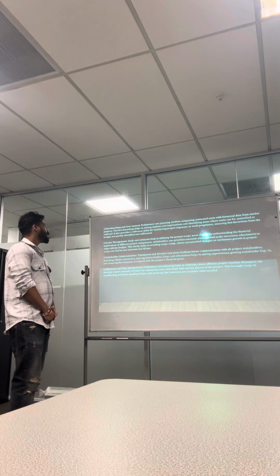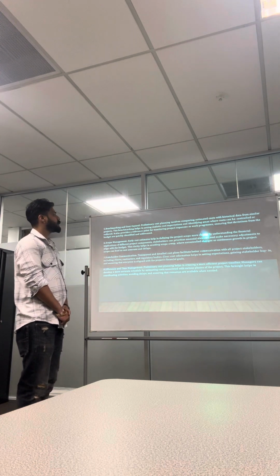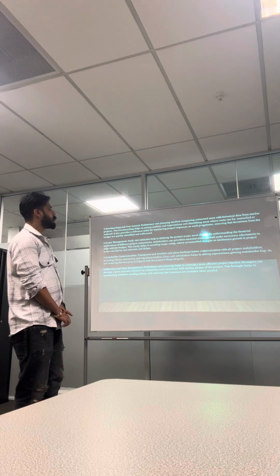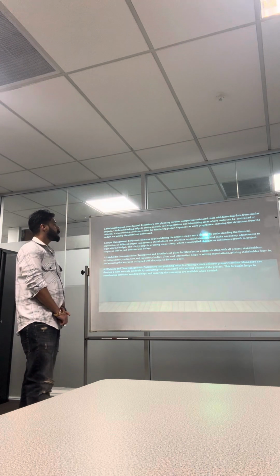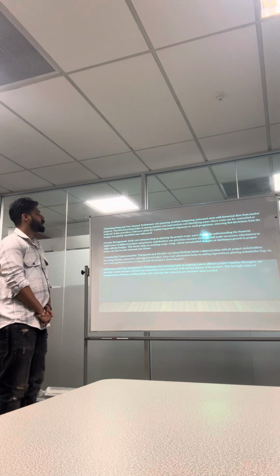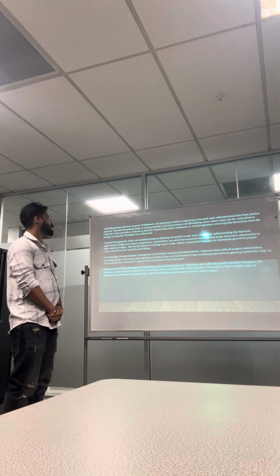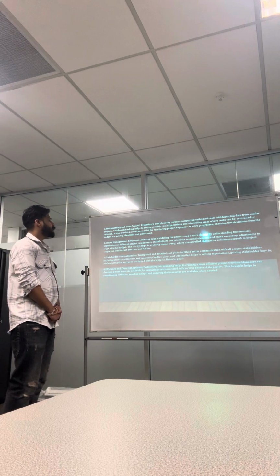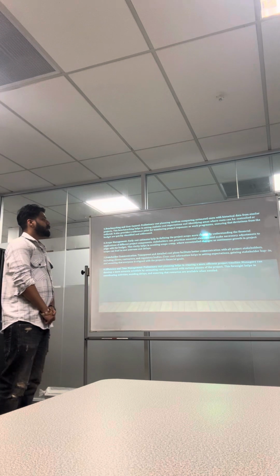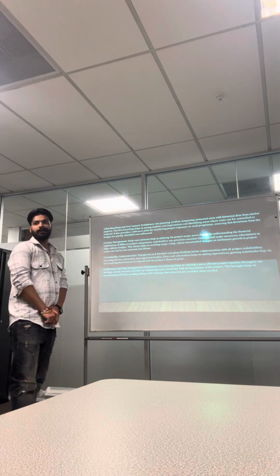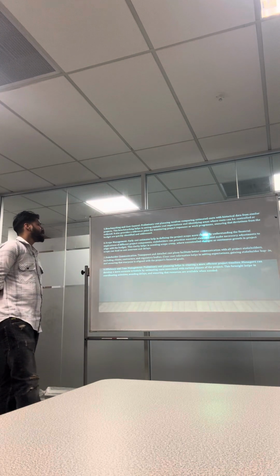Fifth point is benchmarking and cost control. Preliminary cost planning involves comparing estimated cost with historical data from similar projects. This benchmarking helps in setting realistic cost expectations and identifying areas where the cost can be controlled or reduced. It also provides a reference point for monitoring project expenses as work progresses, ensuring that deviations from the budget are quickly identified and addressed.